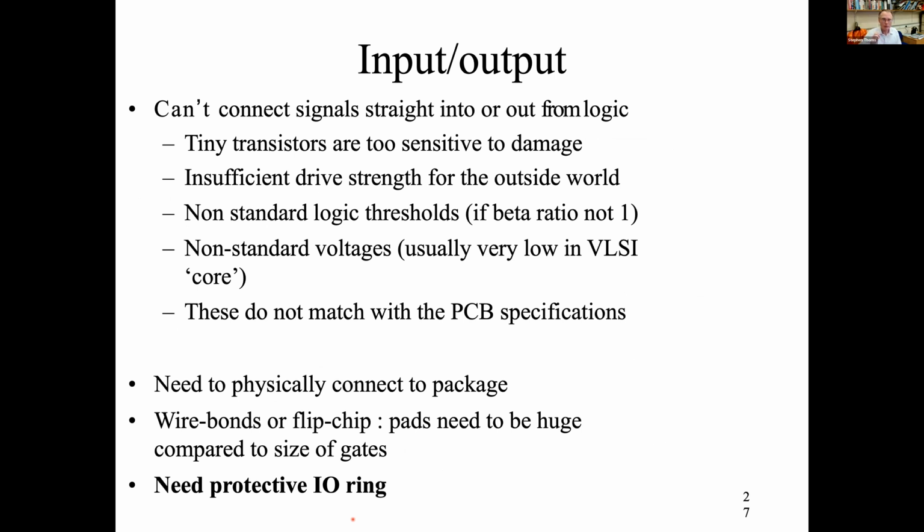Another big area we need to think about is input and output. Up to now, we've been thinking about our inverters, our bigger gates, adders, multipliers, and so forth. But we can't connect a signal from one of these logic devices to the outside world, because these tiny transistors which we're building are very sensitive, and they would almost certainly be destroyed instantly. Moreover, they don't have the drive strength to drive the outside world. They're made as small as possible so they can drive another logic gate within our circuit, but they don't drive an external system.